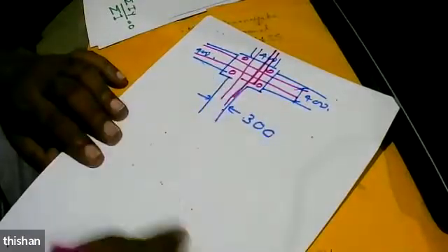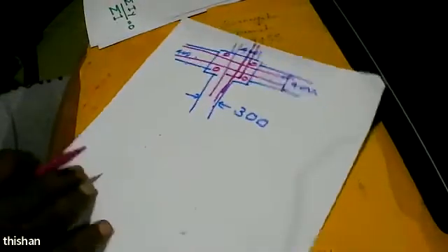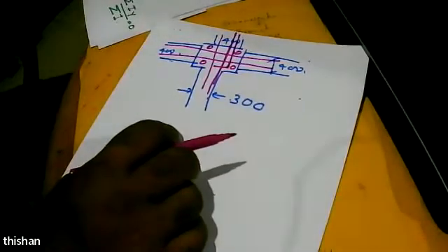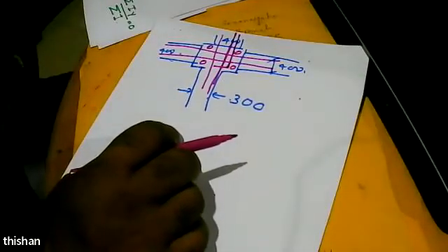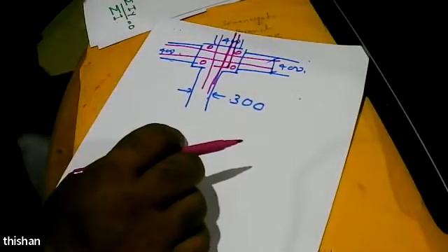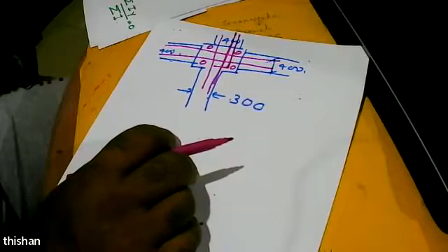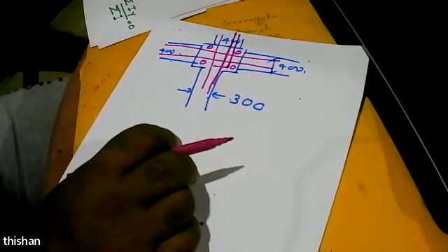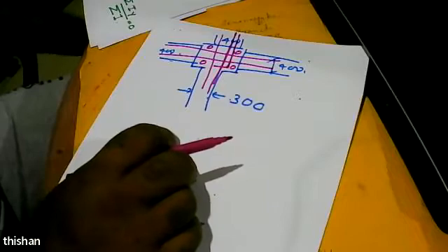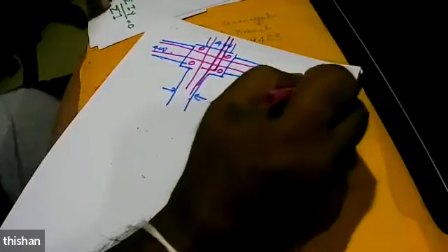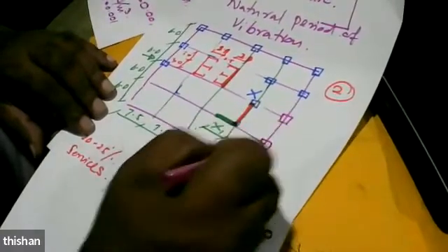Because these are 400, here you got 500, here you got 300. Okay. So you have 300s, 400s, 500s. Now we can accommodate everything. If you are having a column, have 500 by 500. If the beams are 400 by 400, have a column of 500 by 500. That way, you can assure that the reinforcement can be fitted without cranking or with minimum cranking, which is very useful. So if you want to have it, then we have to have columns at these locations.